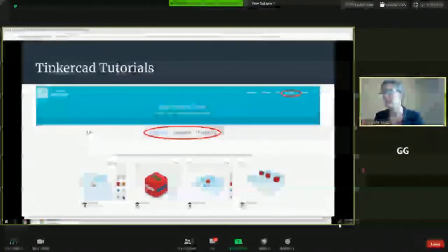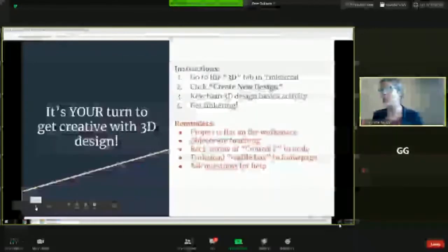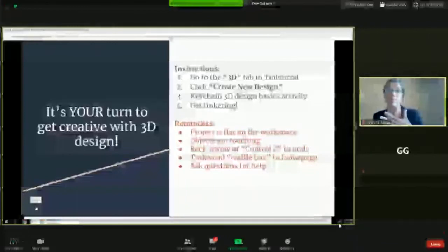And so we're going to get into Tinkercad, and the first thing you'll do if you're in there is you'll see create a new design on the left-hand sidebar, and we're going to design a keychain. I'll jump off of my slide deck into Tinkercad and kind of show by doing, and hopefully you can follow along as you see the presentation. Good old Control-Z or the back arrow to get back to where you were, and again, just hit the waffle box if you get lost.